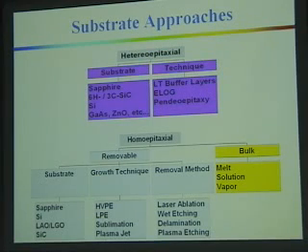And I'm going to tell you about two techniques we've been using. One is using the lithium aluminate or lithium gallate, which is closely lattice matched to gallium nitride. And another approach is some advances we've had, or some good luck we've had with using silicon and a compliant layer that is relatively easy to form. Both of these materials have produced single crystal freestanding gallium nitride. And what I'm going to talk about for the remainder of this talk is this particular substrate.